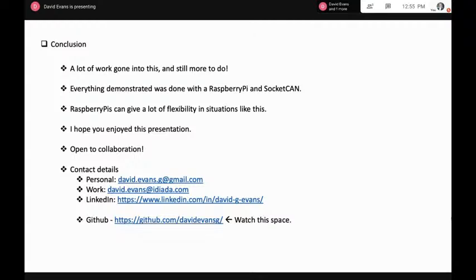It's also worth mentioning that there is an isotp implementation for the kernel as a kernel module. Everything I was showing here, or at least all my applications, were working in user space. There is an isotp implementation for the kernel, which I would imagine is much better than what I made. But I wanted to implement this myself more as a learning exercise than anything else.